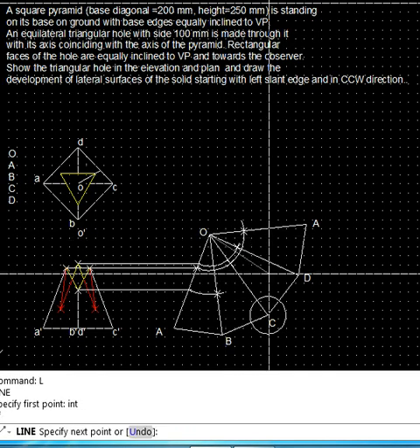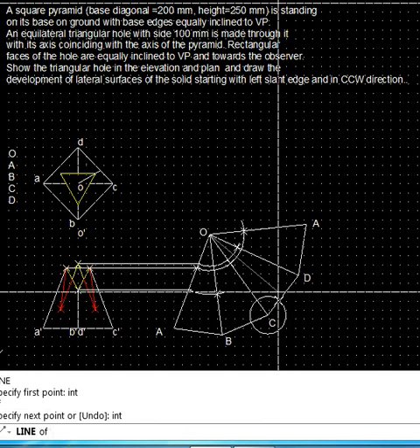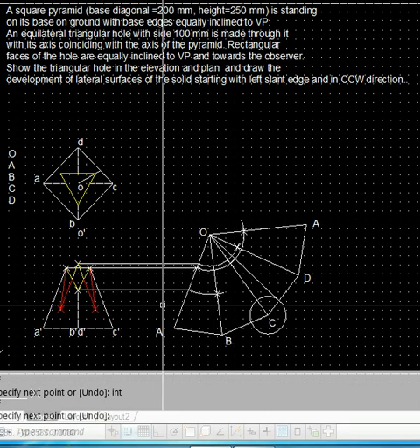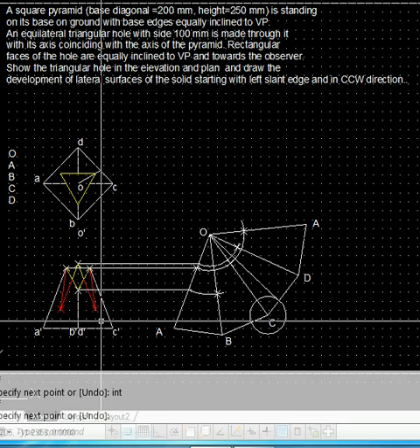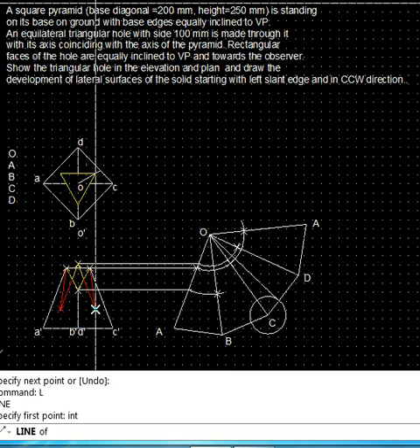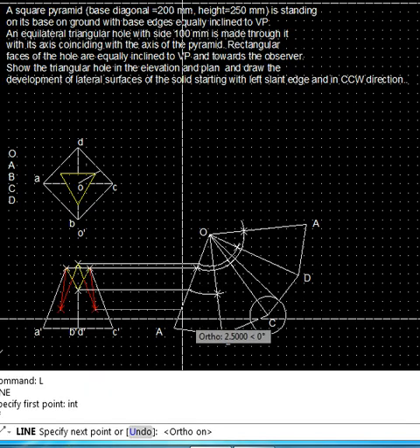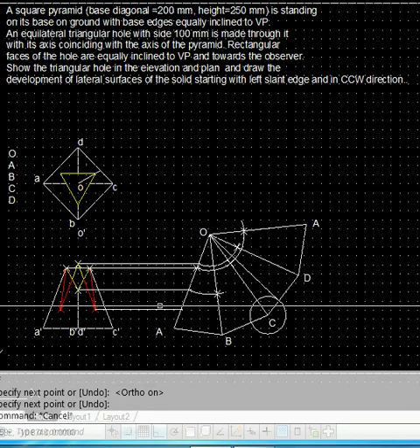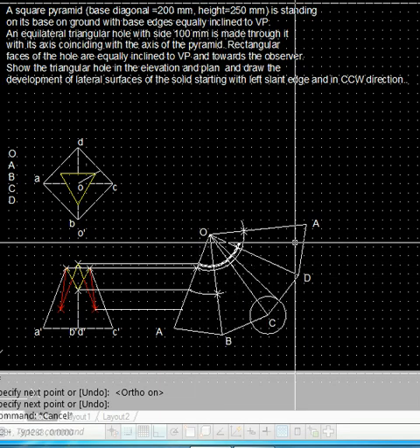The imaginary slant edge which was there on OCD, we locate it here on the development also, and we note that its height was transferred with a line parallel to the base. So the same thing we will need to continue. We transfer it, F8 we do, so we transfer first onto OA, and from there we will transfer it to OC.